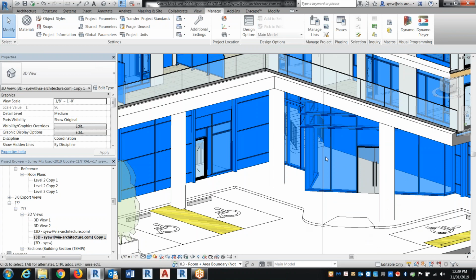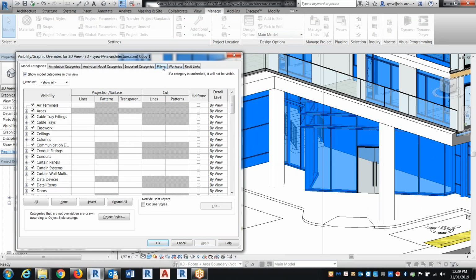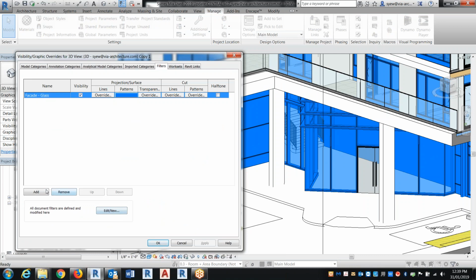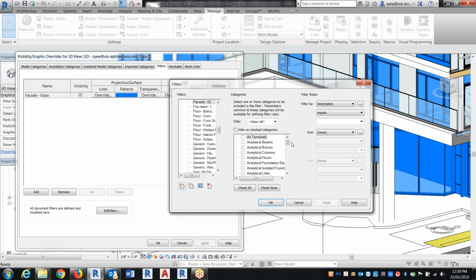So what it would do is that if you want to say this door, that wall, and many other walls, you want to have the same value, then what the filter will do is that it allows you to basically grab multiple conditions where you tell it to be a curtain wall, a door, a wall, and a window.